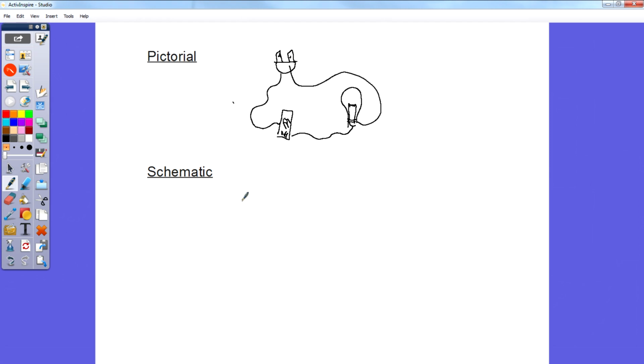But the same drawing as a schematic, the power cord could be one of 2 ways, and most of the time we draw them like this. We put an arrow, meaning line 1, and we'll put L1 here. We'll go to a switch, a light bulb, and here neutral. Now, which one was faster for me to draw? The second is schematic. Yes.